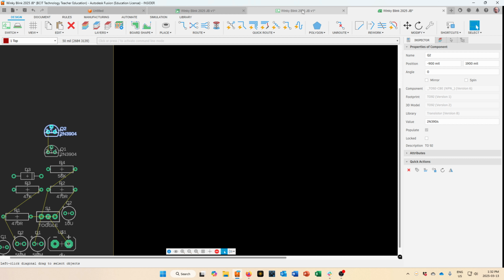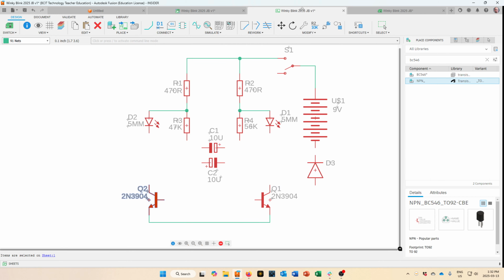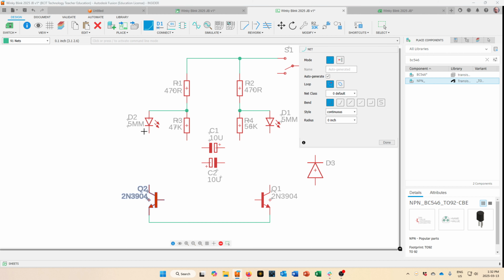And so let's come back and let's finish up our schematic because we know we've got the right part here. Okay, in our schematic, the diode comes down here because the transistor turns the diode on and off. That happens on both sides. And the 56K resistor comes down here and connects to the base, or you could use a 47K resistor and it comes to the base.